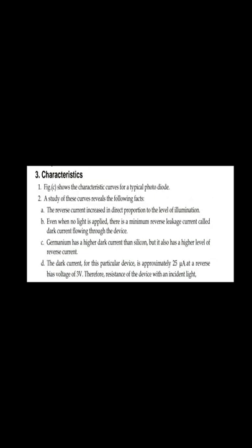So we have to calculate the reverse resistance at reverse voltage 3 volts and the corresponding current. The dark current for this particular device is approximately 25 microampere at reverse bias voltage of 3. The resistance of the device is 3 volt by 25 microampere, which gives the dark resistance 120 kilo ohms.